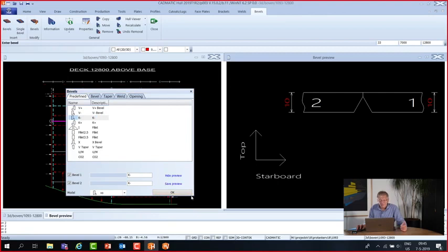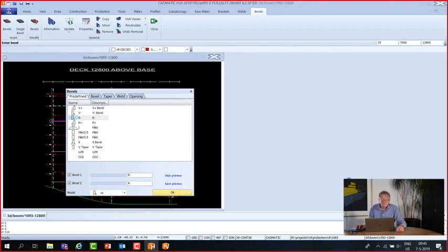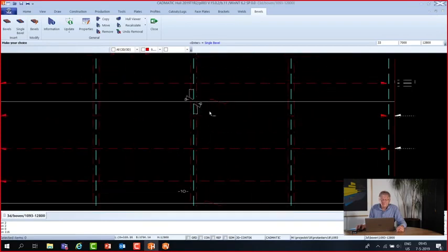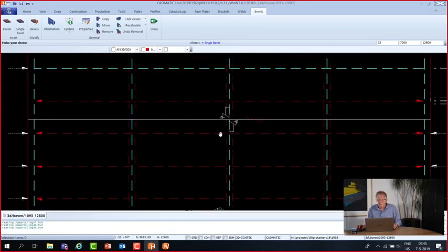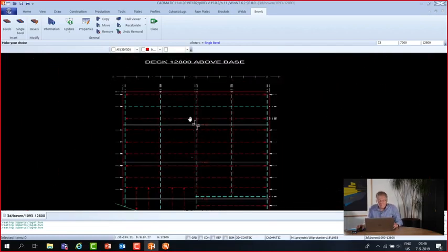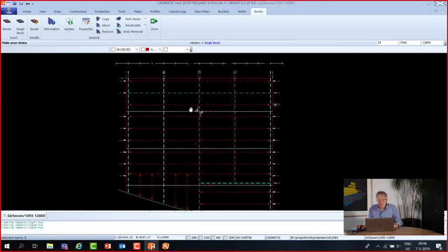I could save this. Only the position of the symbol is a bit bad, that's why I don't often do it. But anyway, now the information for the bevel is sent to the cutting machine, or first to the nesting and after that to the cutting machine, and the plate is cut according to this bevel. Alright, that's about the welds and bevels.